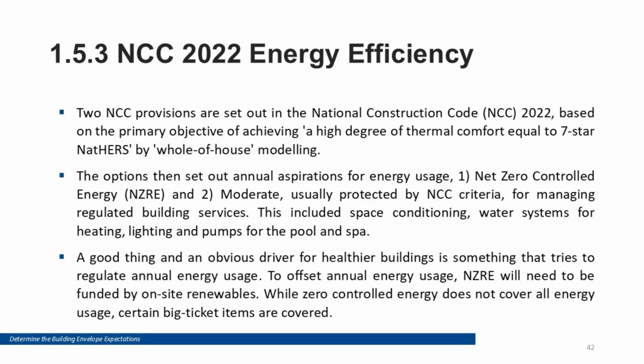NCC 2022 Energy Efficiency. The NCC sets energy efficiency requirements for building fabric and services. It's increasingly focused on real comfort and lower energy demand, not just paperwork compliance. On site, this means specified insulation levels, sealing details, glazing requirements, and service provisions must be built exactly as approved. Quality checks often focus on junctions, penetrations, and window installation, because that's where thermal and air leaks commonly occur.